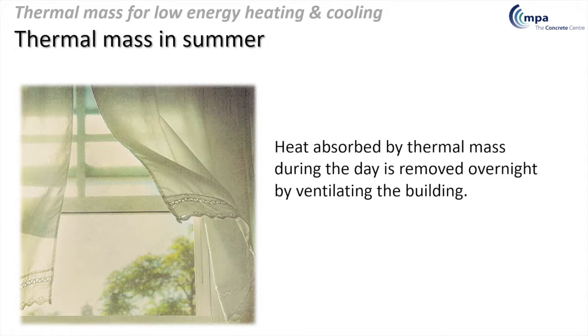So thermal mass is really good at that, but it is important that you ventilate the building properly to get rid of that accumulated heat. So you need quite large air change rates to do that. So perhaps we need to give more thought to summertime ventilation than perhaps we currently do, particularly in dwellings.